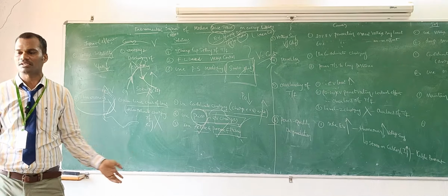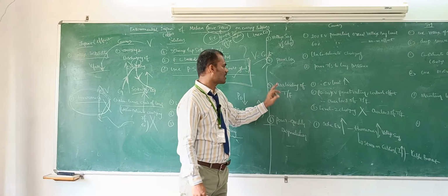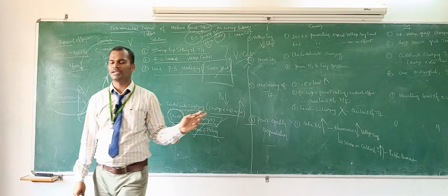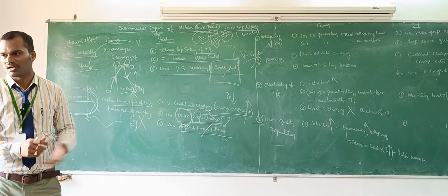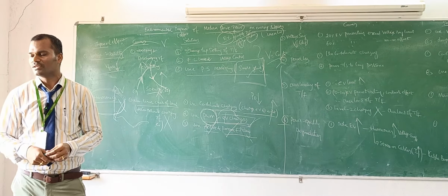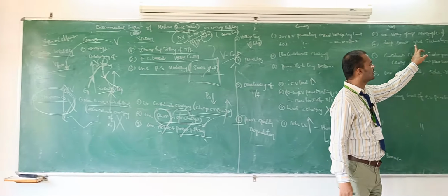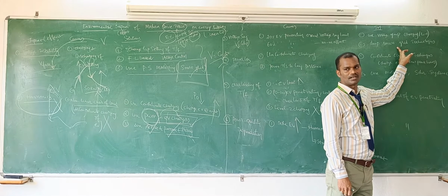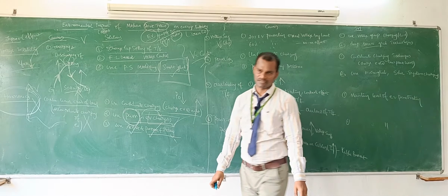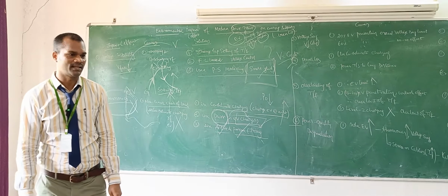If they are not improving, this will create problems like voltage instability, harmonics, voltage sag, power loss, overloading of transformer, and power quality degradation. All these problems will be created if you inject more electric vehicles into the market. So before you inject, you should optimize your substations and your power grid to a system like microgrid as well as smart grid. In foreign countries, they have the latest smart grid or microgrid systems. So this technology can handle all the power quality issues created by electric vehicles.